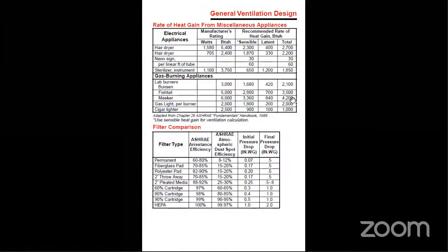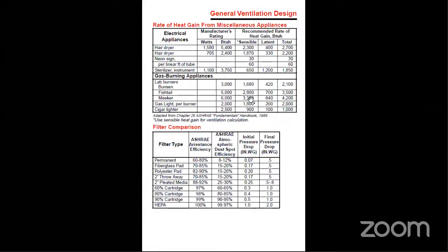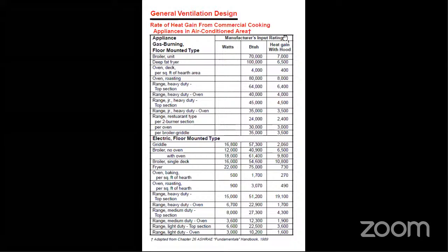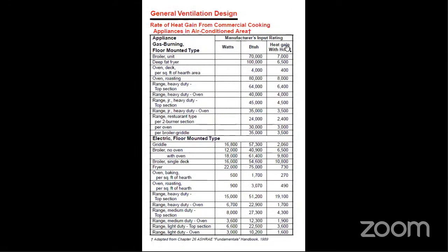You can convert into watts also. Similarly, if you have other electrical appliances like hair dryer or gas burning appliances, you can get the total heat gain, sensible as well as latent heat gain. I hope you got the answer for your doubt.